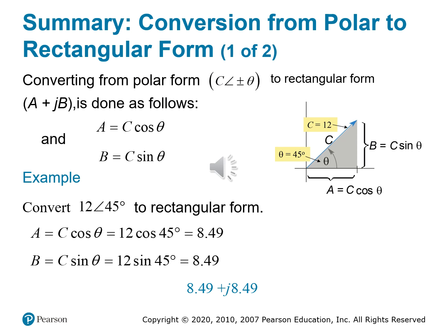Just like we did with the impedance back in the inductor podcast, where we had inductive reactance, which was jX sub L, and the imaginary component, which would have been the X sub L. That vertical axis, remember, was all imaginary, just like here. So the example that we've got, let's run these numbers, or plug and chug, right? A is equal to 12 cosine 45, and that gives us 8.49.